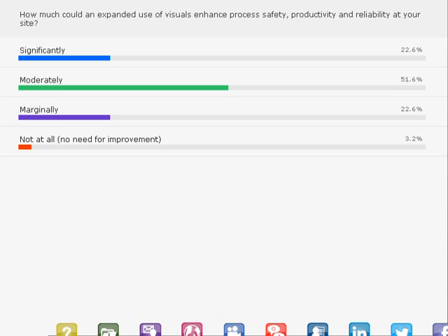Let's jump over now, Bob, and see if we've got any questions here. There's one question that says, how are visuals different from warning signs? My experience is that once people see a sign, they ignore it from there on out. And that's one thing you have to be sensitive to, because the visuals are very specific. So it's going to be on a piece of equipment about a specific point. Think about doing lubrication, doing a PM. You're labeling lubrication points. You're numbering the points in a sequence. You have a lubrication diagram. So it's designed to be a visual cue.